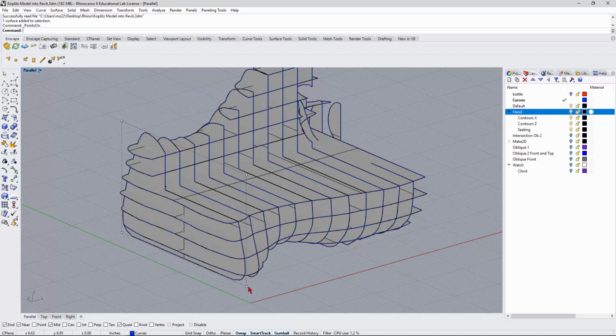So this is called a trimmed surface, and the rest of that surface is actually still there, but it's just hidden from you based on this trim. And so when it gets into Revit, Revit has a hard time, I think, making a wall from surface out of that. Oh, sorry, wall by face out of that. So I figured out a little bit of a hack, so you're going to have to decide if you want to do this or not.